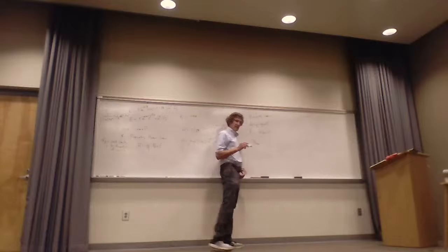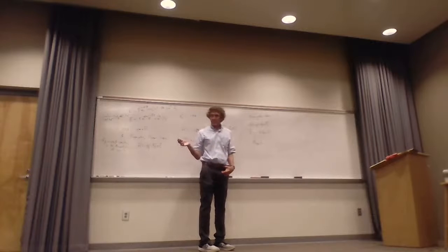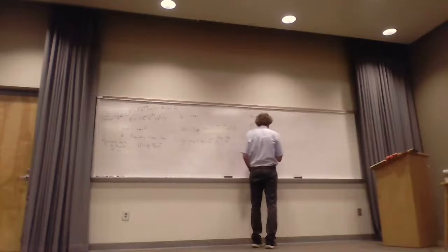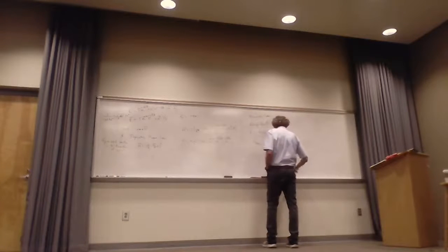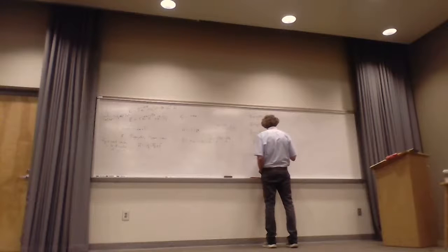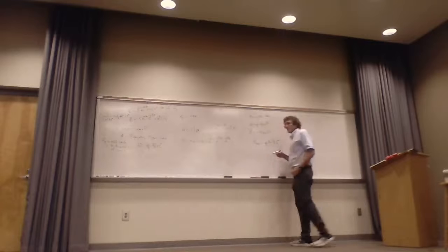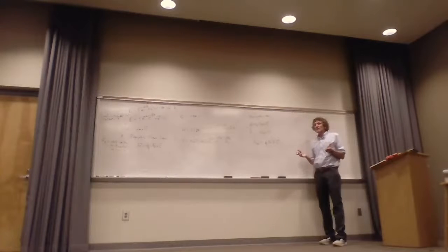So when we take power, P average, this is going to be the density in watts per meter squared. Before I do that, I always go back in the day when you had circuits, and you said power for transmission lines was 1/2 the real part of V times I conjugated. Do y'all remember doing that? That was for power when you dealt with circuit problems, right? How much power was flowing. It was voltage times I conjugate, and you took the real part, right?